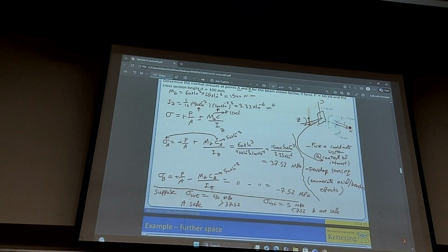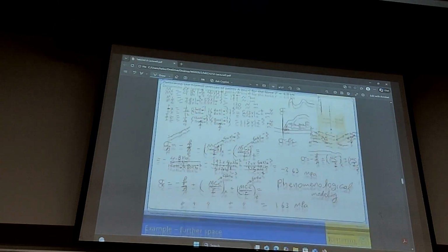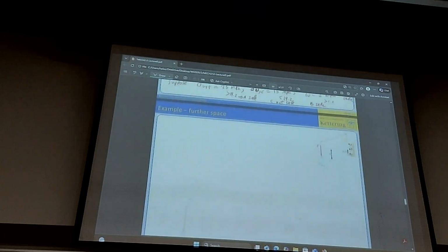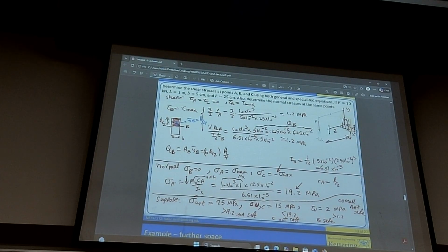You're talking about bending. The force causes bending, but really the point was what Bruce said specifically. The force is not creating a pulling or pushing effect. That's why we do not put any force over area. That one from the top only creates bending. Let me go back there. This one creates only bending. We do not put F over area of that at all, because that's not really force. If it were fixed from underneath, if we load it like this, yes, it would all be F over area also included. But it's open to move downward, so really it's not axial loading.